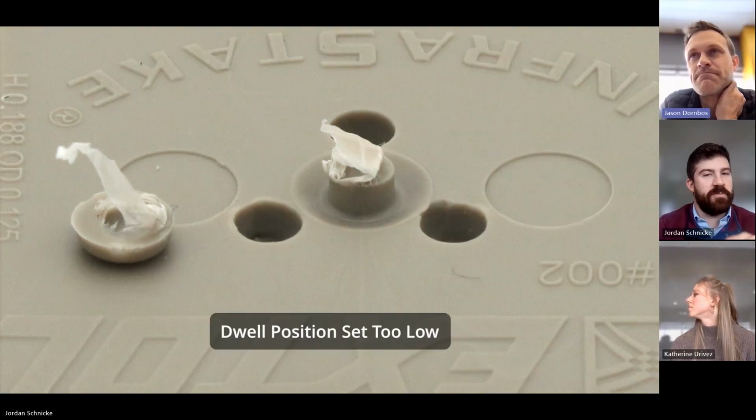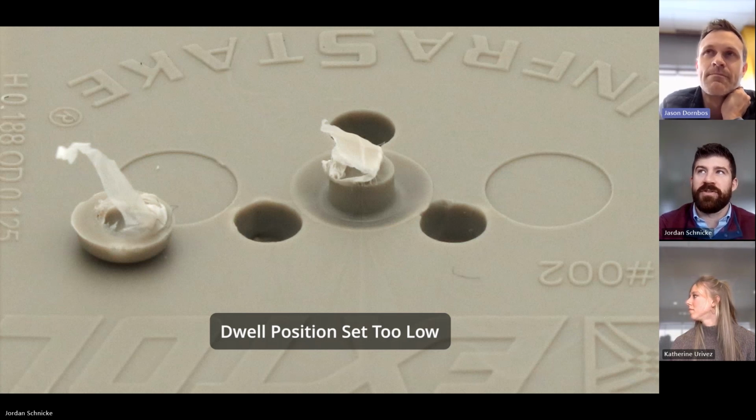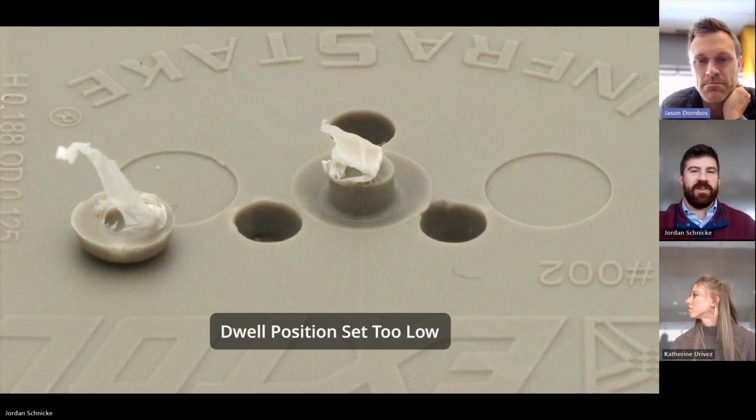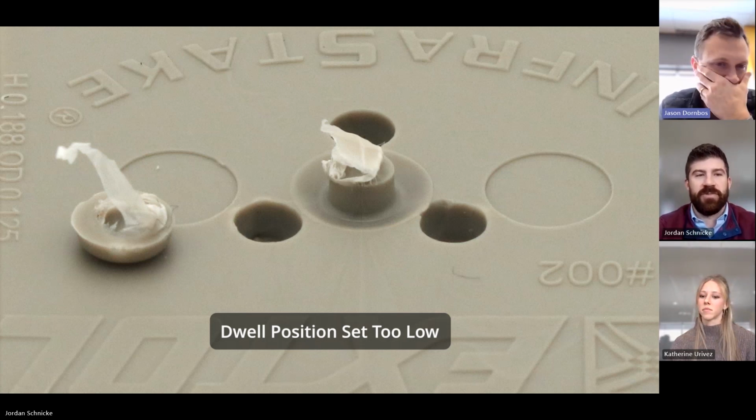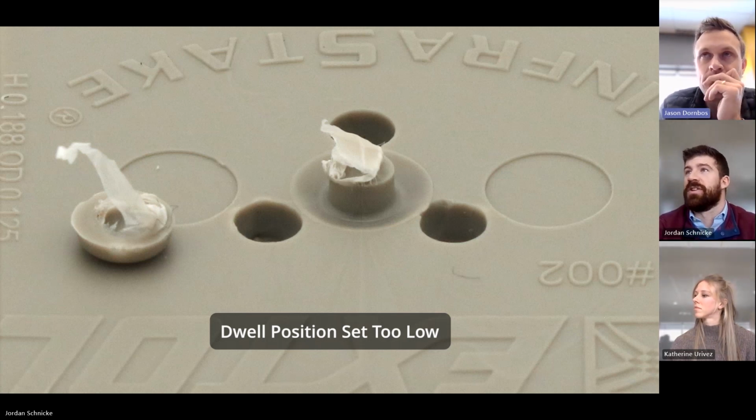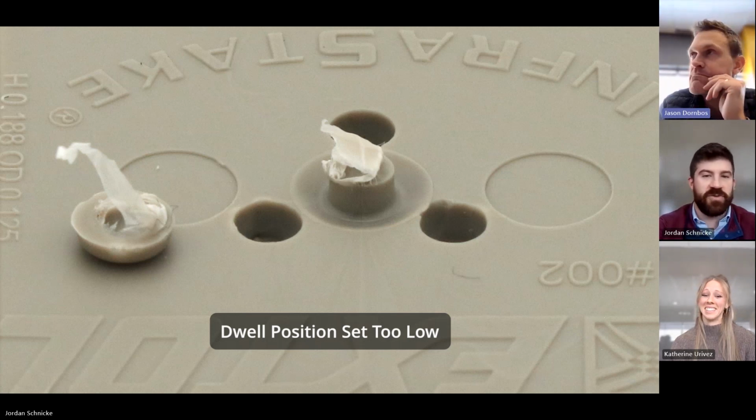And it's calculated based off what your actual melt temp is. So that's going to scale. Like if you're up to 800 degrees, it's only going to heat for X amount of seconds. If it's set at 500, it might heat up for 40 seconds, but it'll scale based off what that is. Just so you're not melting through an entire part or damaging a module or anything like that.